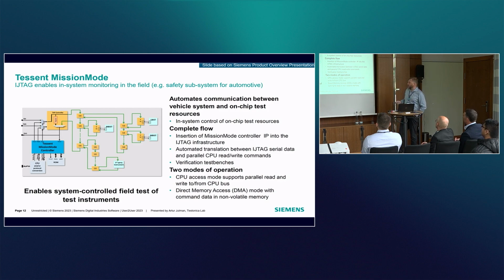Mission mode enables the embedded software to take control over reconfigurable scan networks, IJTAG networks, to do real-time monitoring of different parameters on the chip while the chip is running in the field. So it's like doing some measurement in operation.